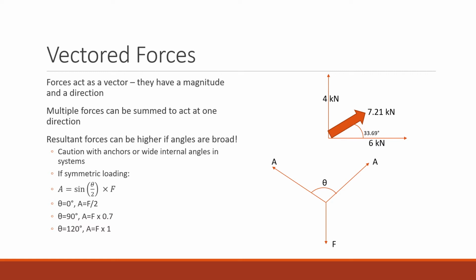This is because there are forces in the x direction now, in addition to just the forces in the y direction. So it's almost like the load became heavier because you brought that further apart. As you bring that even further apart, out to 120 degrees, you're effectively carrying the same load on both legs as the load itself. So you've doubled the load effectively as you bring that internal angle out.